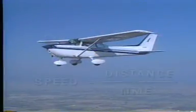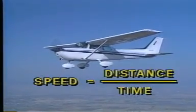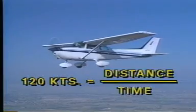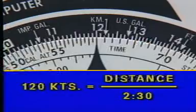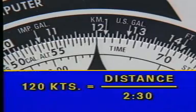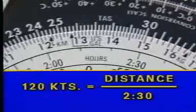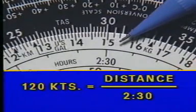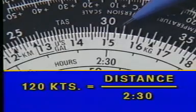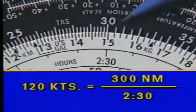You can also use the computer to find the distance flown in a given period of time. For instance, at a ground speed of 120 knots, how far will you travel in 2.5 hours? First, set the speed index under the ground speed of 120 knots. Then go to the C scale and locate 2.5 hours or 150 minutes on the B scale. Directly above this number on the distance scale is your answer, 300 nautical miles.